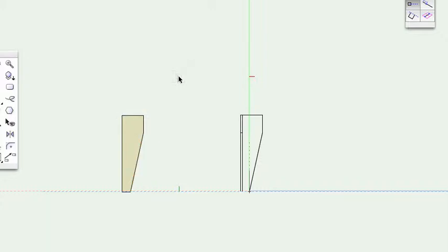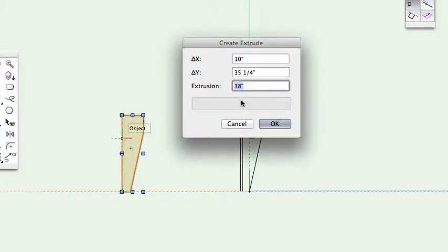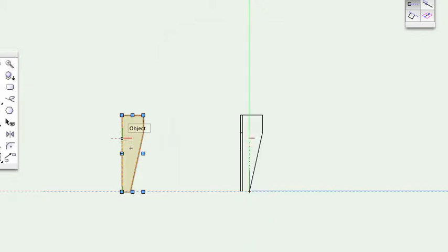And there's your leg. Still have to extrude it: Command E, select it, Command E, and make the extrusion 3/4 of an inch. And you have a leg. And you'd do the same thing as far as getting the 45-degree miter on it. All right, I just wanted to show you that. Let's go back now to plan view, Command 5. All right, so now we're back to our leg in plan view.